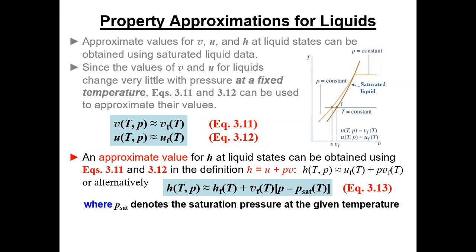And so this little equation in black over here, what they're saying is enthalpy, we know in general, is a function of temperature and pressure. Well, so we can take the temperature and go look up the internal energy, forgetting about the pressure, unless it's just tremendous. That's kind of the assumption that we're doing up here. And then we can look up the specific volume at that temperature and multiply by the pressure.